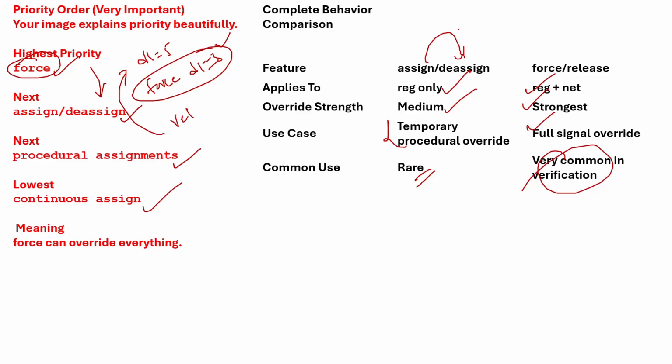Most of the combinational circuits only, because we are giving the input and immediately getting the output. Then a wire can't store any value. That's why we are utilizing assign. That assign will get the value immediately.